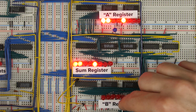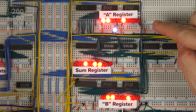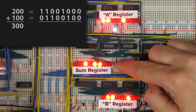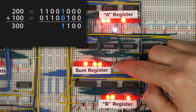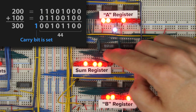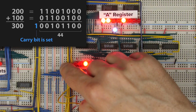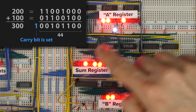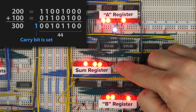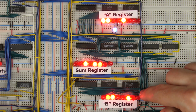But now let me put something into the B register. Okay, so this is 100 in binary, and so now we've got 200 plus 100. Well, the result should be 300, but 300 doesn't fit in 8 bits because with 8 bits, we can only go up to 255. So instead, what we have here is 44, which is the remainder we're left with since we don't have a 256's place. But instead, the carry bit is set. And so this tells us that the answer in the sum register isn't really the sum of 200 plus 100, which might be a good thing to know.